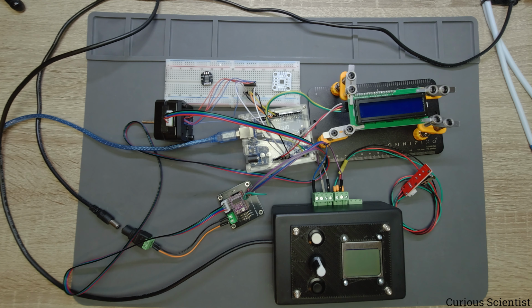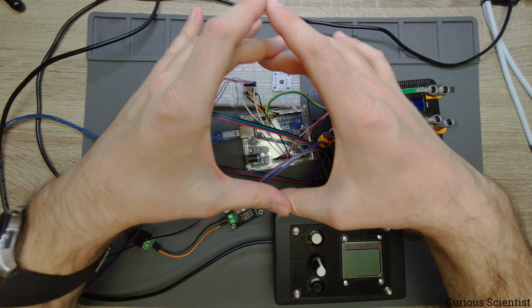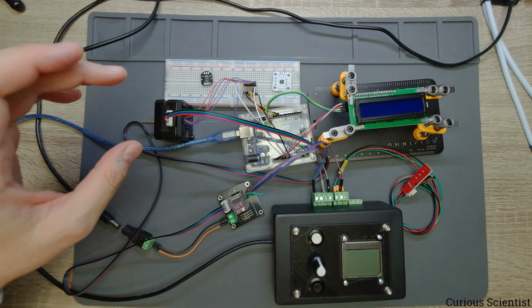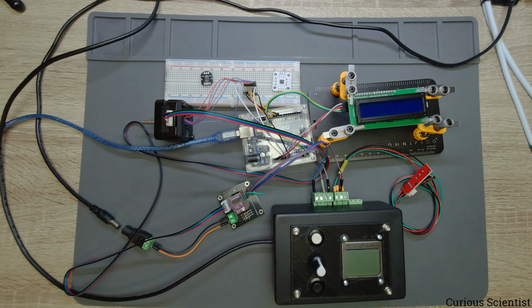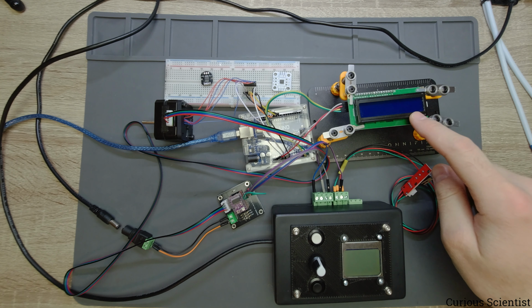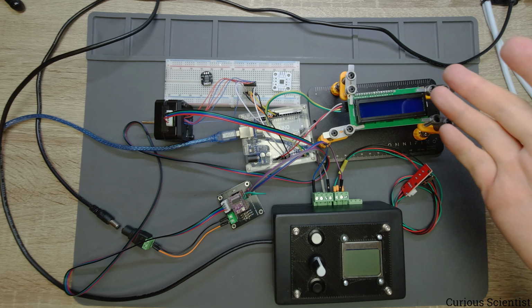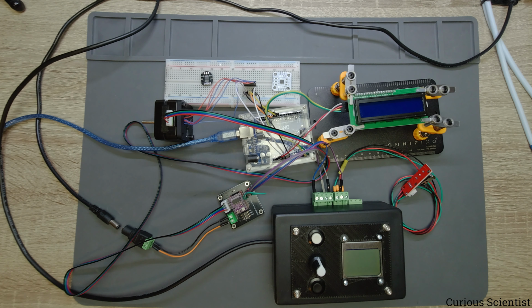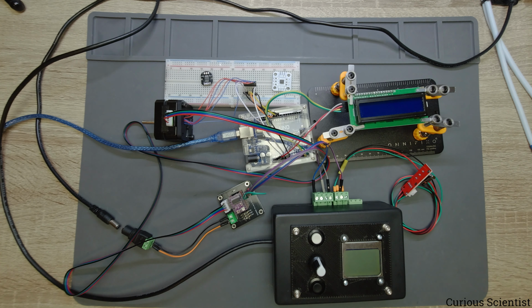On my website you will always see the correct wiring, but this top row here is nothing else than the detector connected to an Arduino Uno on the standard SPI pins, and then we have a 16x2 LCD which is just displaying a few numbers. What we will see here is the RPM and the total angular displacement, so basically the accumulated turns times the degrees.